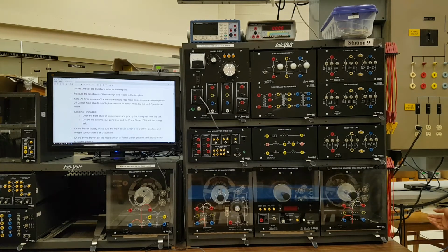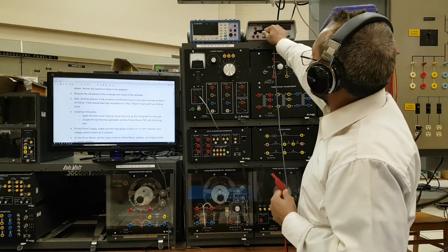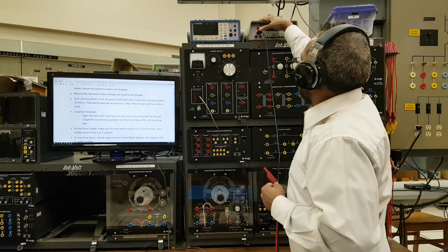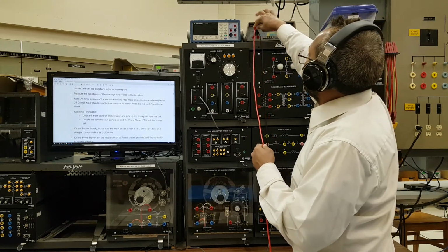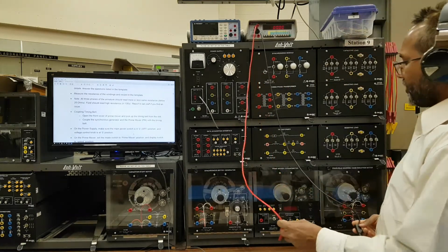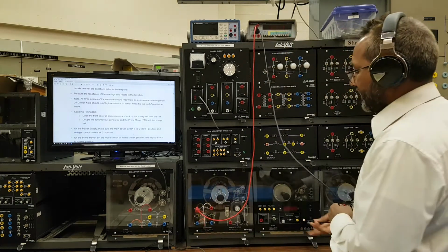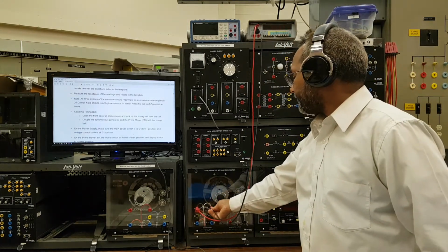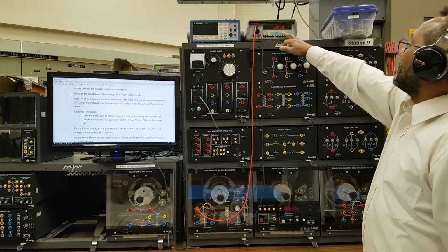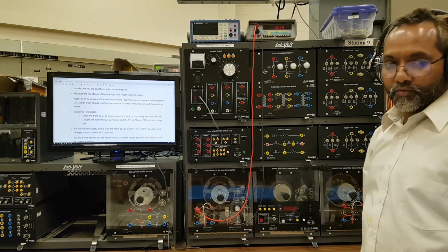So what we do is take 2 color wires. Let us take black and red, because the terminals here are black and red. I'll connect this to the common terminal, and this is the ohms resistance measurement terminal. If I want to see the resistance between these 2 ends, I just connect here and here, and you can see that it's showing 12.14.